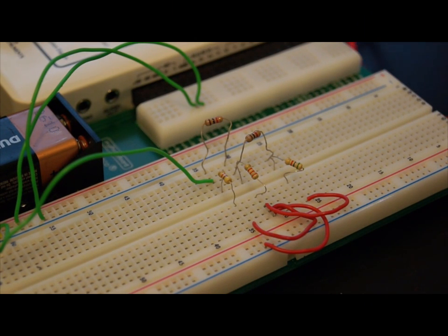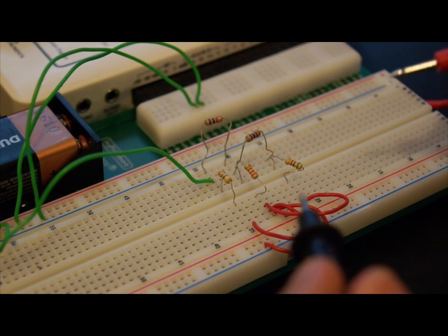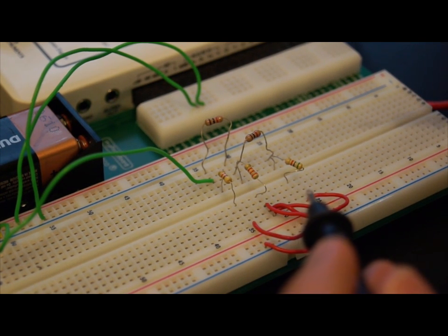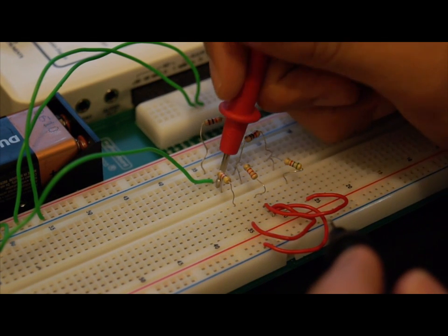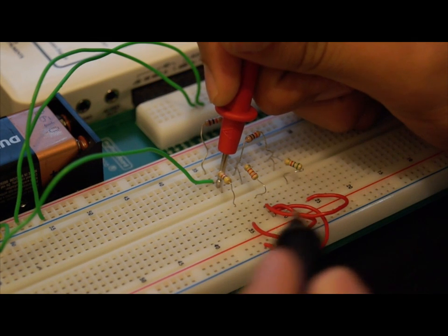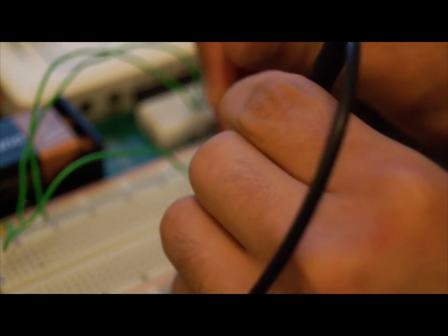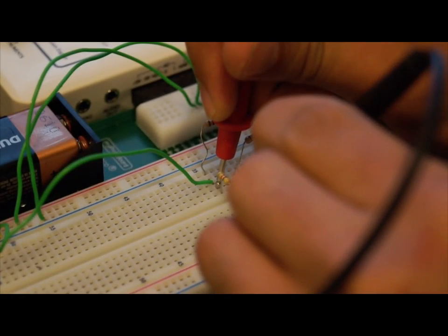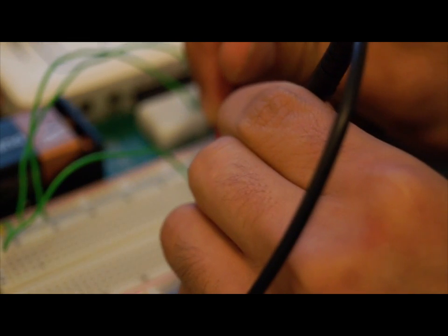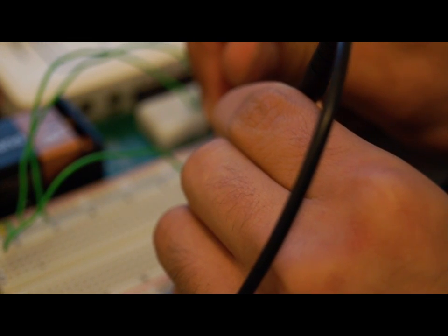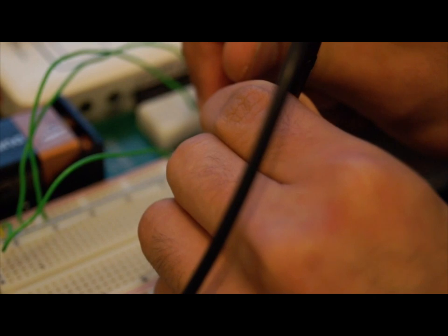With the digital multimeter loaded, you can now use the two probes that come with the myDAQ to measure the voltage across each resistor. Place the positive probe on one end of the resistor and the negative probe on the other. Wait for the measurement to load in the digital multimeter and record it in LabView.